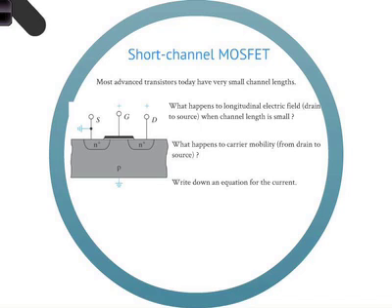Current is just flow of electrons. So your number of electrons, how fast they are moving, velocity, that's it, right? Speed of electrons multiplied by number of electrons, that's the current. Nothing to it. Number of electrons, you know. How many carriers are there in the inversion channel? Qn, right? We just looked at that. So you just leave it at Qn. You don't need to actually write anything down more complicated than that.